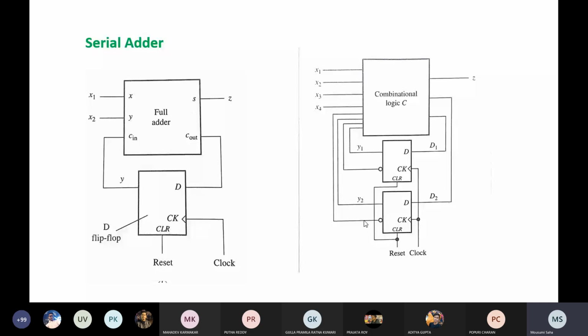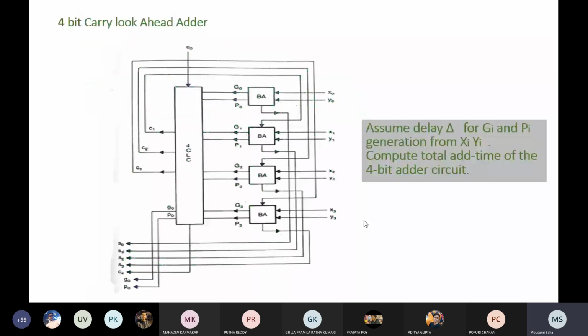Based on that you should have that number of bits of inputs in your circuit. If you need 16 bits, you should consider x and y as 16 bits, and then you should have 16 basic adder circuits, and consider 16 bits in your 16-bit CLA circuit.